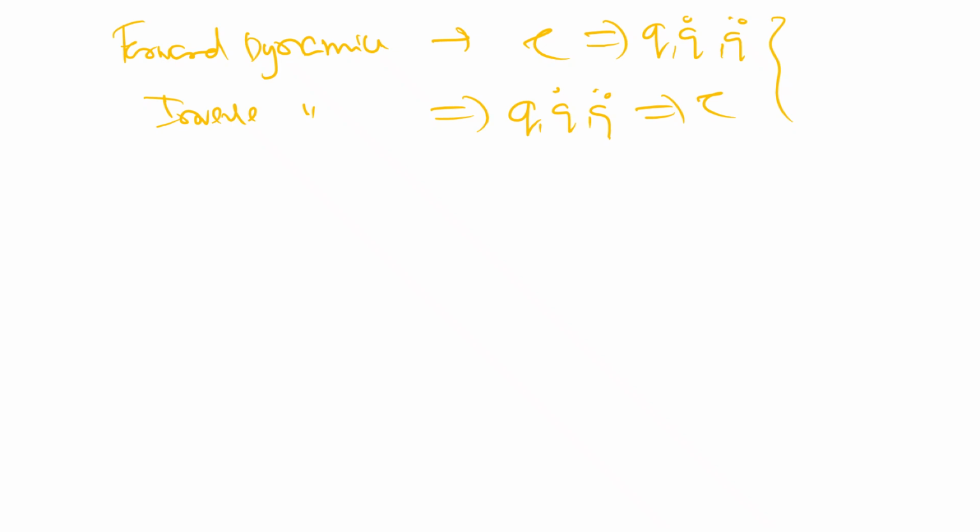So what is dynamics? Dynamics gives the relationship between, suppose this is the manipulator, if you give force, how the force propagates inward towards the base, and then you have theta dot and theta double dot. So here force is given, and you have to find the relation between the applied force or moment and, as the result, the joint motion and joint velocity. With this, you should be able to find out the torque.